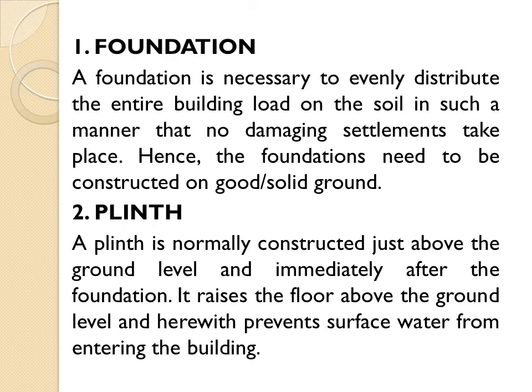In the plinth, various types of materials are filled. This plinth raises the floor level with respect to the surrounding ground level, so it prevents surface water from entering into the building.